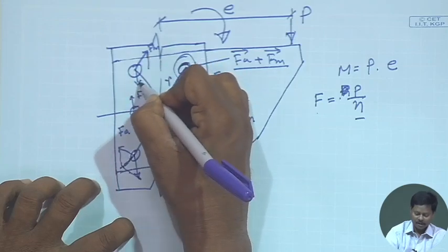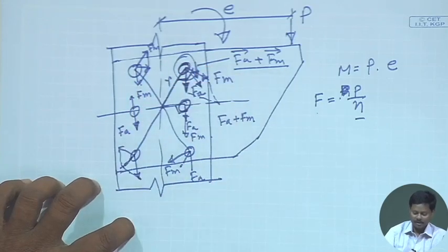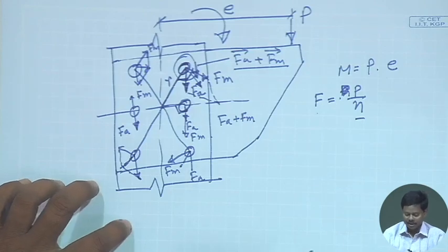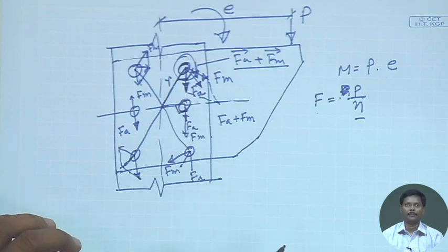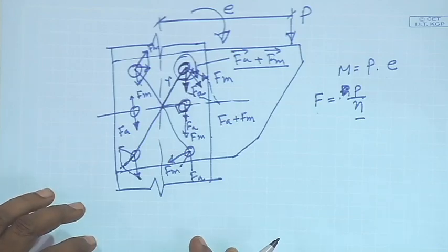Therefore, the resultant F R will be in this direction. So, for each bolt the resultant force will be different. We have to calculate the force coming on each bolt and see which one is critical, so case by case we have to consider and find the critical one.